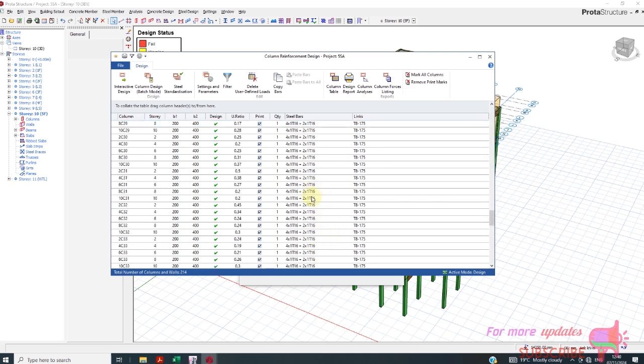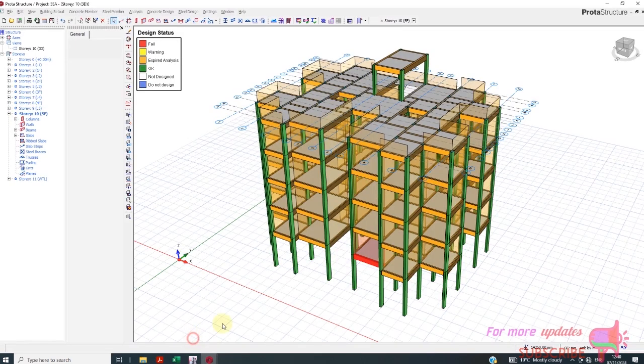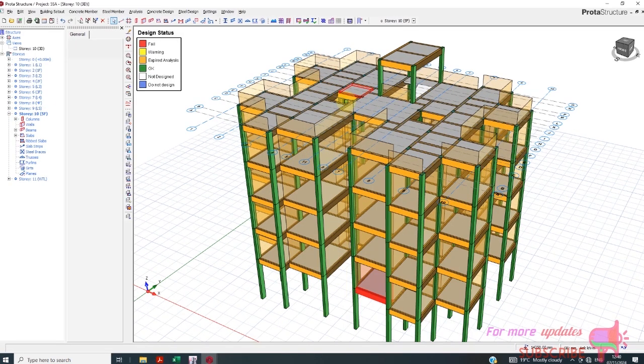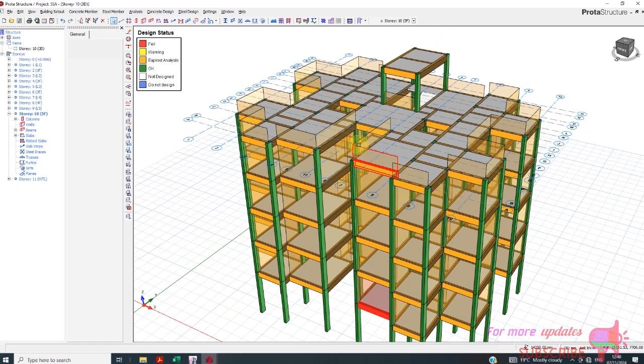So I'm going to go with the value for item. So I think every time you are designing, don't underdesign, don't underload your slab. The value should be not less than 2.5 extra dead load on slab.